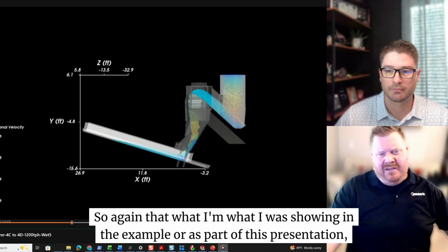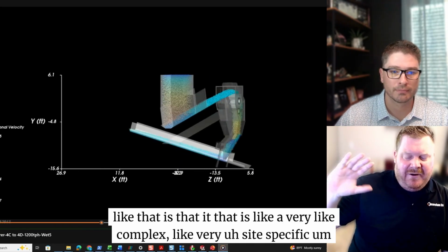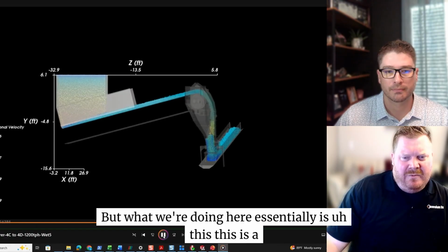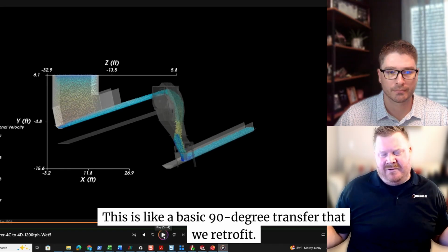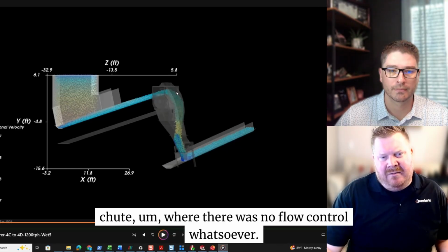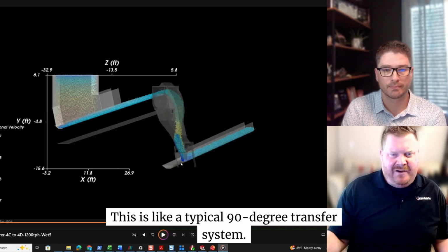Again, what I was showing in the example as part of this presentation is a very complex, very site specific application. But what we're doing here essentially is a basic 90-degree transfer retrofit. So our specialty here is where this used to be a boxy head chute and load chute, where there was no flow control whatsoever. So this is the head pulley, this is the tail of the conveyor. This is a typical 90-degree transfer system.